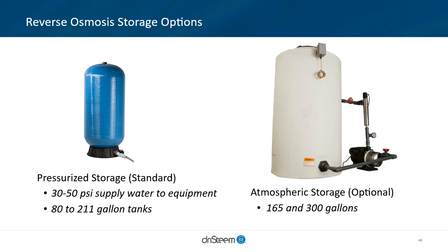The other thing with pressurized storage is that the labeled capacities are total capacity. We have to be cognizant of drawdown: one side of that bladder is pressurized air on the initial setup side, and the other side is the water side. So that 80-gallon tank will roughly hold about 24 gallons of water.